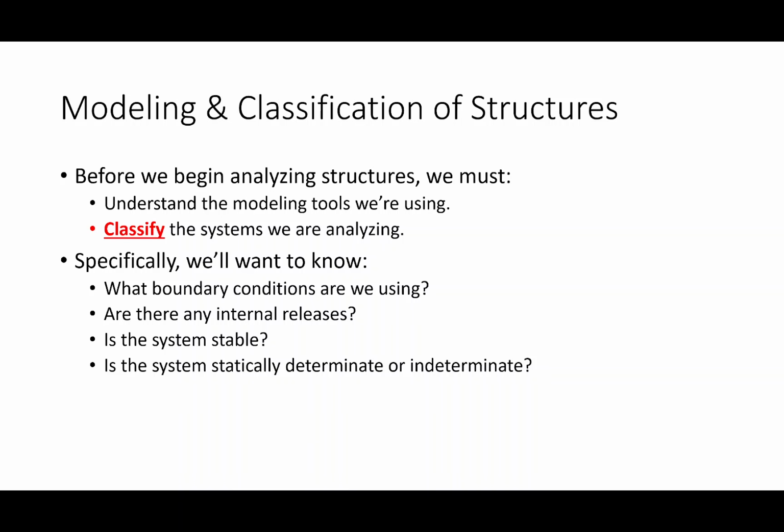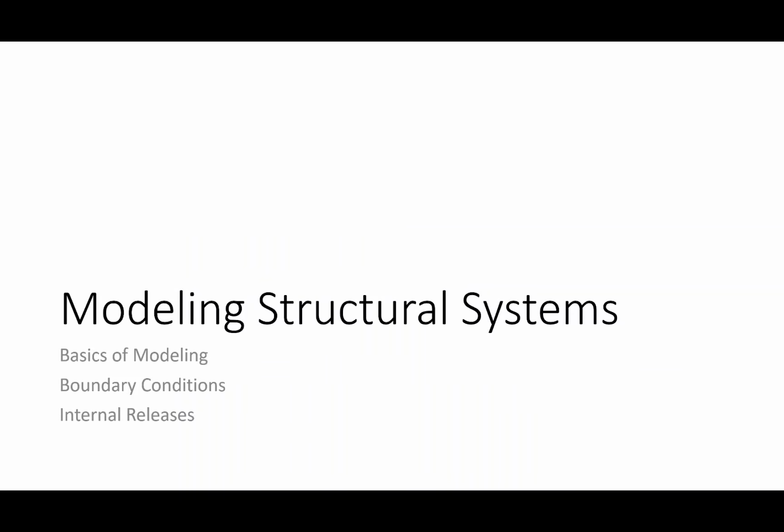Obviously, we don't want to be building any structures that are unstable, so being able to determine whether or not a structure is stable is important just from a practical standpoint. But whether or not the structure is determinate is very critical in order to figure out the type of analysis that we're going to perform. Indeterminate analyses are a lot more challenging. Actually, that's probably the wrong way of saying it. Indeterminate analyses use a lot of determinate principles, but really they're just a lot longer to do. They take a lot more time and a lot more math. And they also require more information about the structure in order to be able to do it.